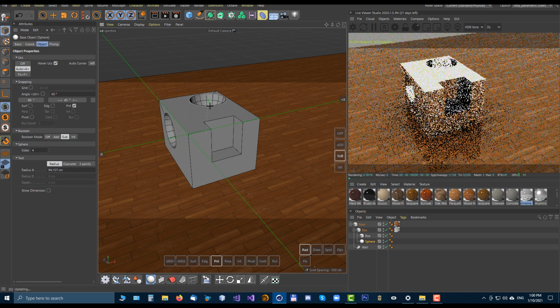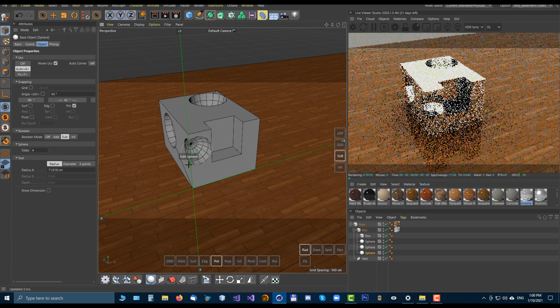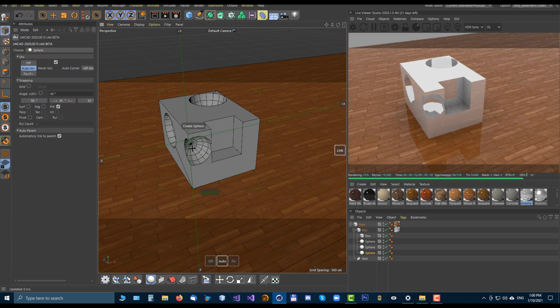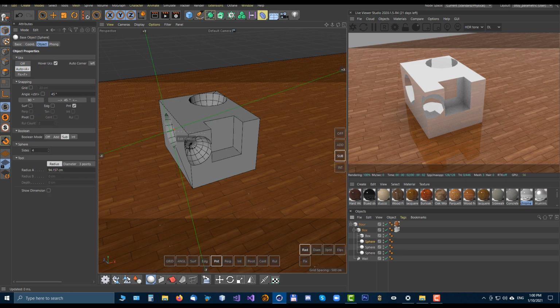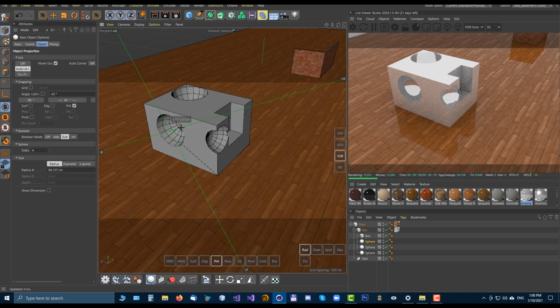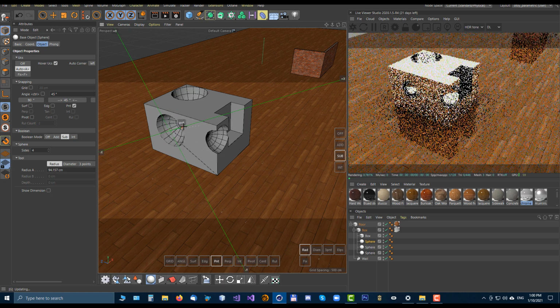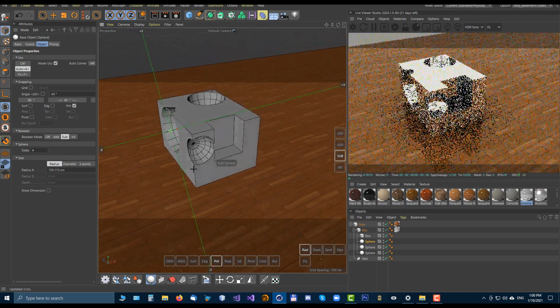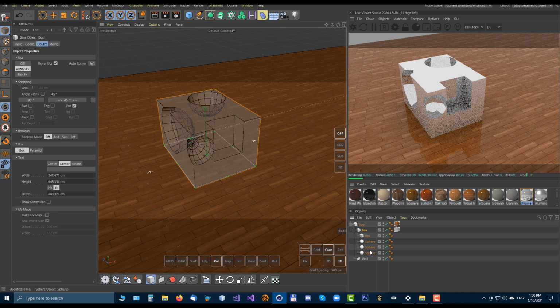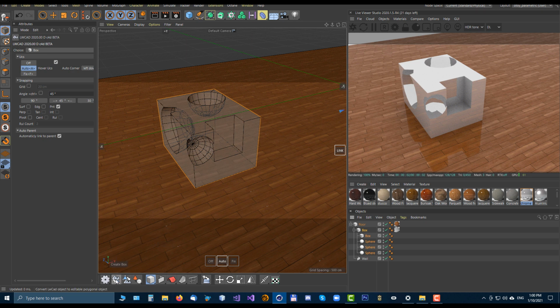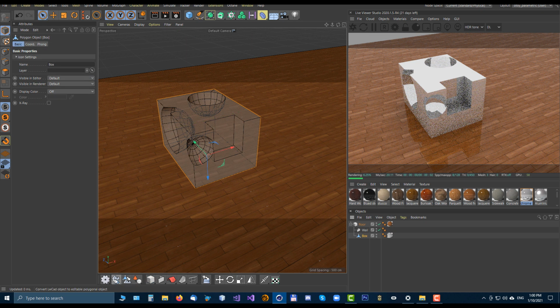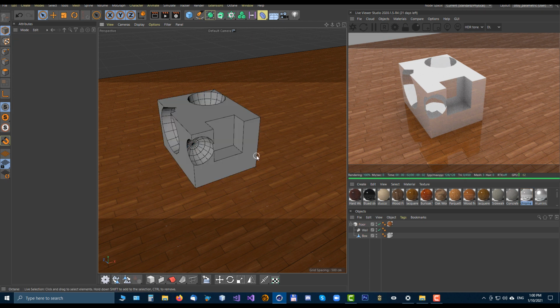It is a pretty fast way to do Booleans, and these Booleans are still non-destructive because anytime you switch back, let's say this sphere, you can adjust each step of the Boolean. But once you select this and convert into LwCad object or into mesh, so let's freeze them into mesh, now it is destructive. So you will no longer be able to adjust these Booleans.